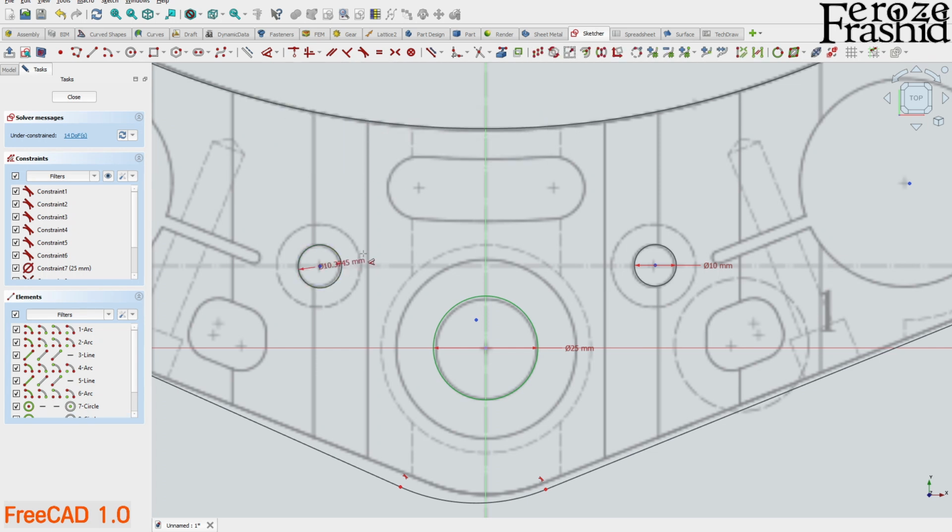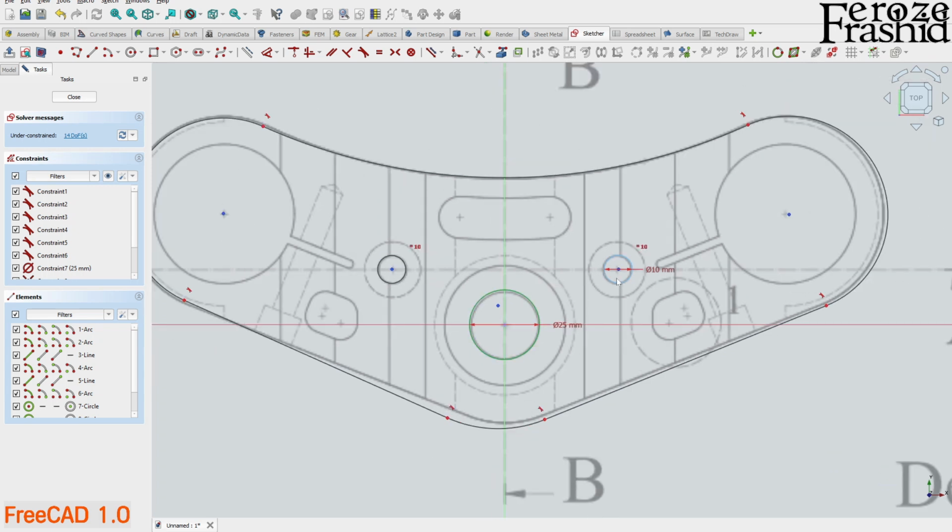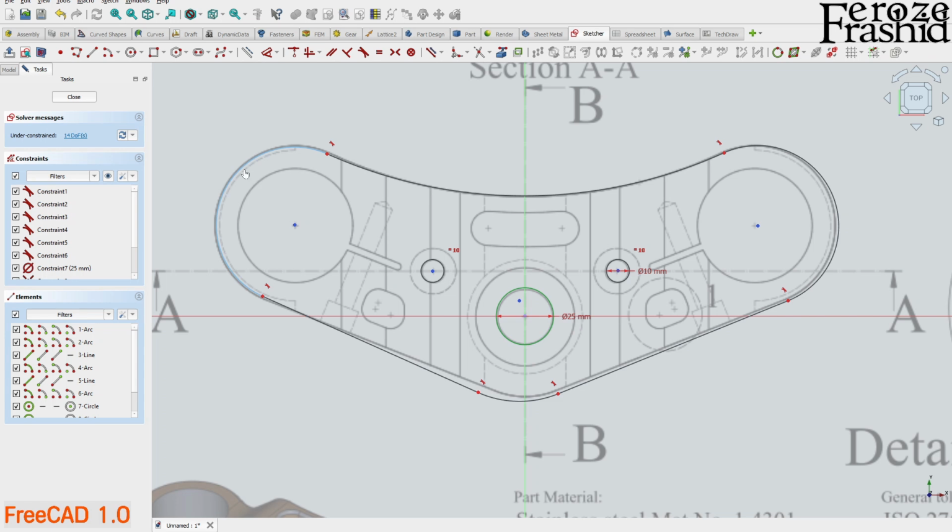So select the edge, hit D on the keyboard, and you can say this is 10 too, or we can take these 2 edges and make it equal. So that's also one way to constrain, which is actually a preferred way to apply constraint. If you have something equal to something else, apply it. Like these 2 should be equal. So E on the keyboard, that makes it equal.